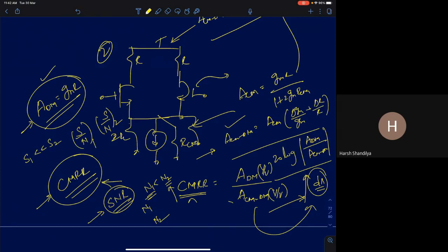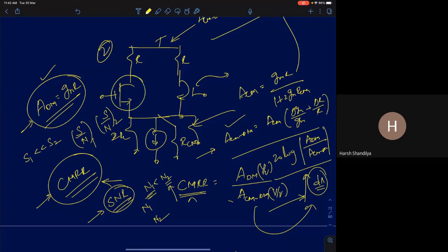They're two different things. I just told you how to look at it intuitively, and to explain why CMRR makes sense, I compared it with SNR. That's it, but they are not directly related. Noise is a very generic term. It can be because of the MOSFET's thermal noise, which we will see in later courses how to characterize, or noise in the supply voltage, or noise in the previous amplifier stage. Anything can come into the system.